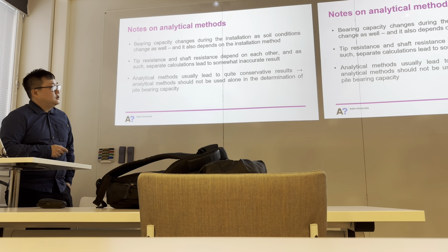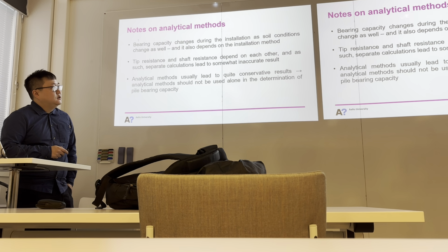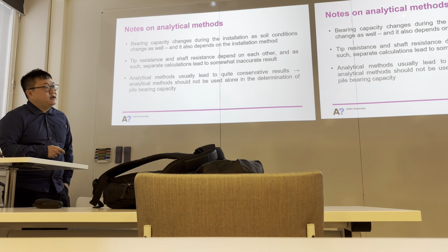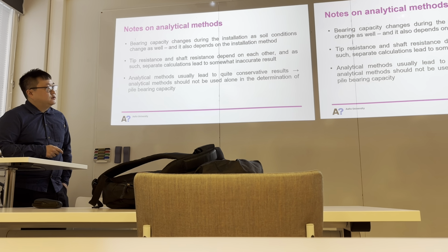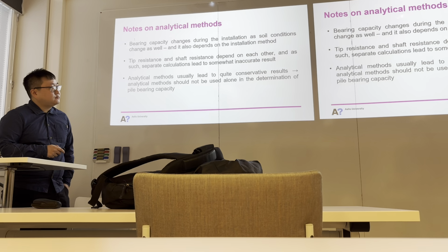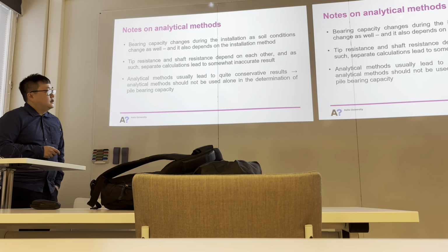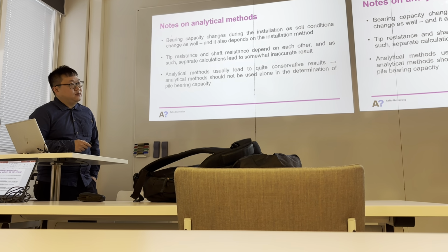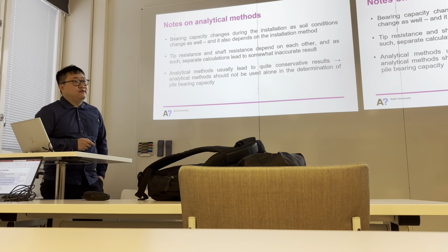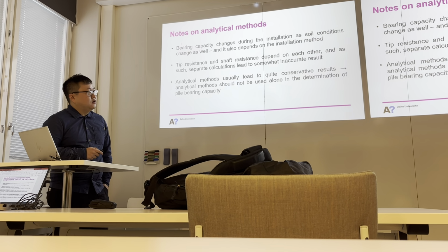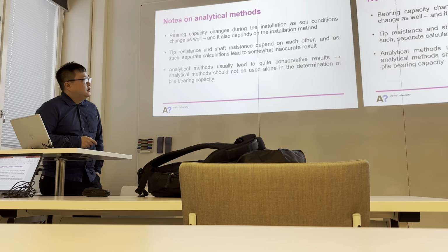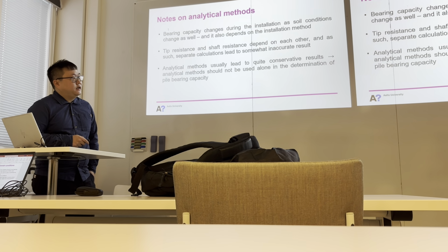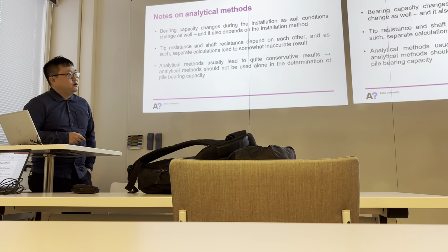Secondly, the tip resistance and the shaft resistance depend on each other, but we do separate calculations, so it may lead to inaccurate results. Finally, the analytical methods usually lead to conservative results because they are based on equations instead of the real geological conditions and testing. So the analytical method should not be used alone here, and we can also use some load testing